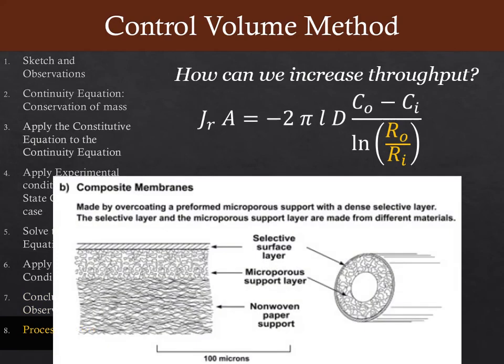Well, we could change our tube so that our wall thickness was much, much thinner. Okay, the thinner we can get that wall, the Pyrex, the faster this could go. One way to do that and still have mechanical stability, right? Because if we get this wall too thin, the pressure moving the gas through is just going to cause the walls to collapse.